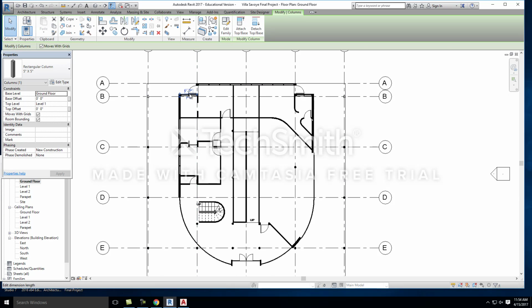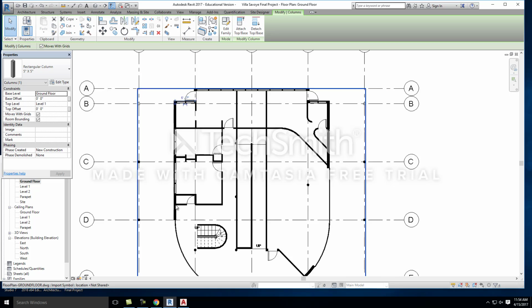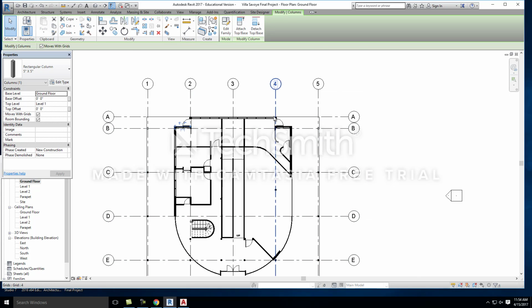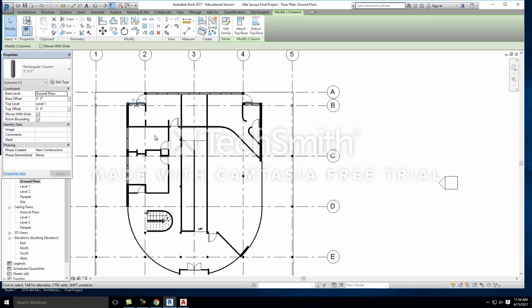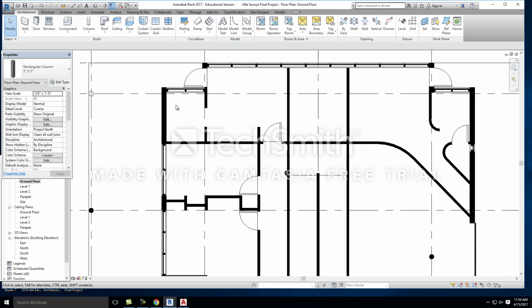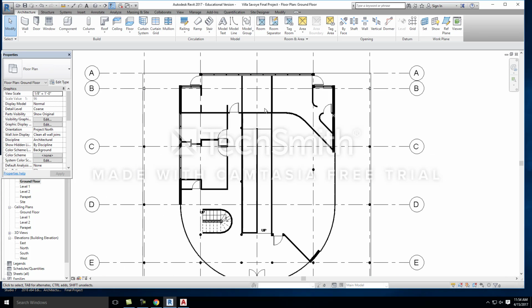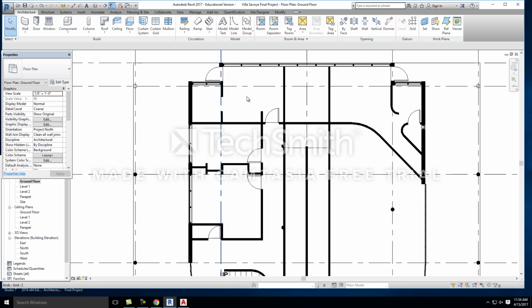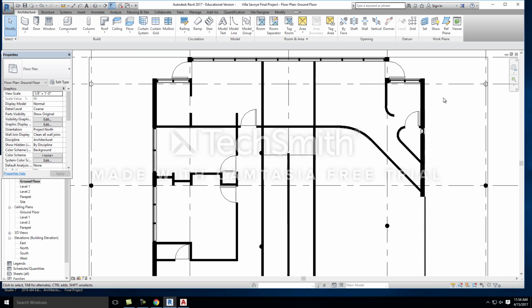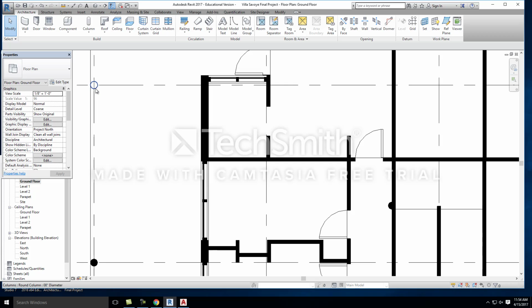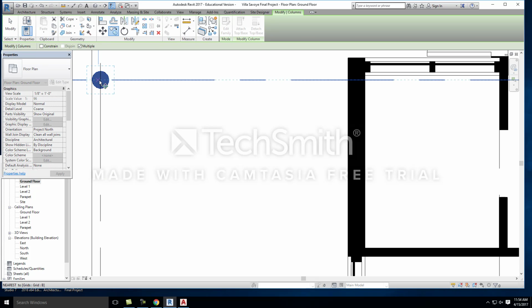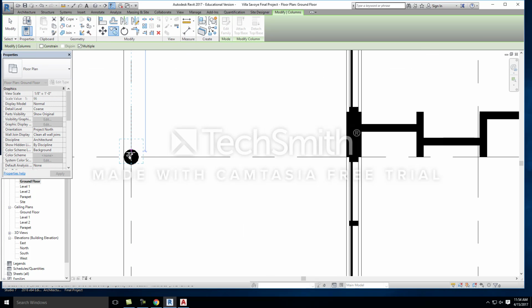I think that's correct. All of the exterior wall is masonry, which can support its own load. So that's probably why you don't see a column there. Steel needs columns to support. Okay, up to you. If you want to add those columns, you can certainly do so. I'm just going to add the circular ones just for simplicity purposes right now.